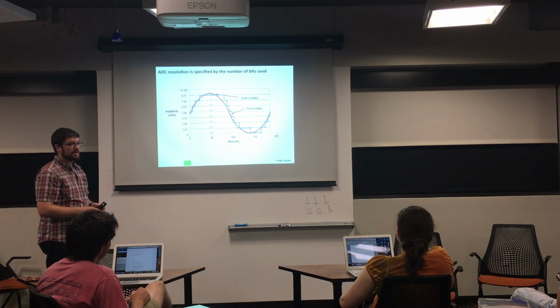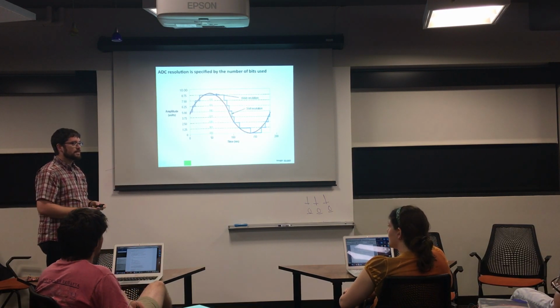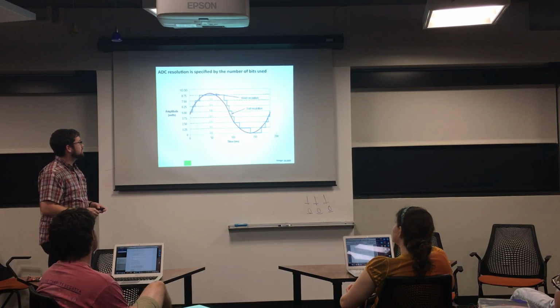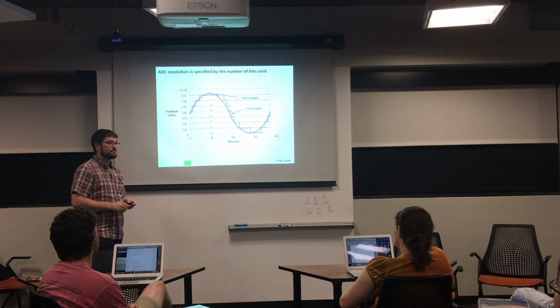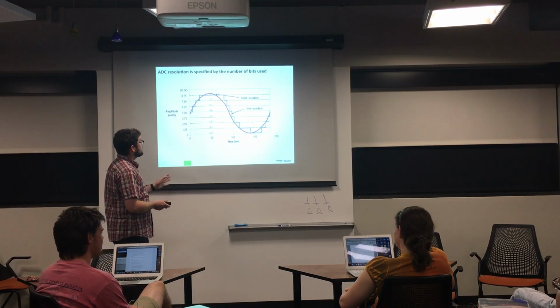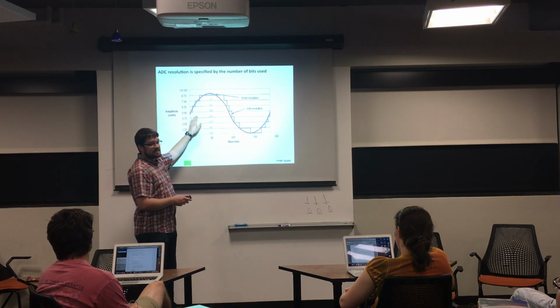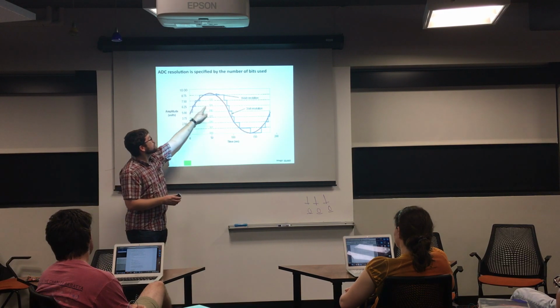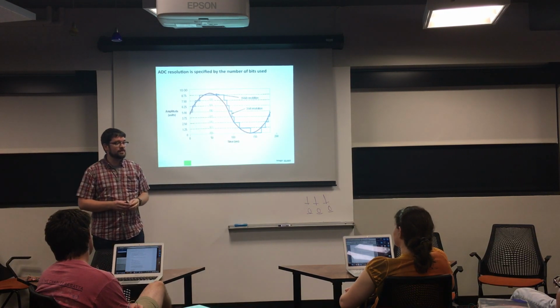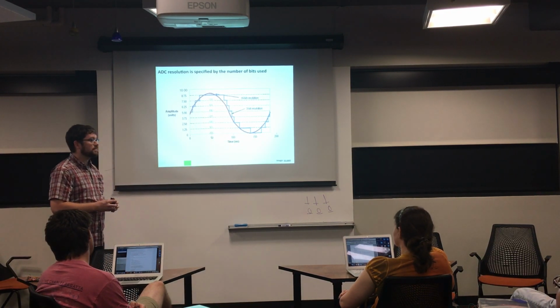I mean, if you're thinking about, I'm going to load some sample to 10 megapascals normal stress, is it good enough that each step on your analog to digital converter is over a megapascal? Probably not. But if you go to something that has 16 bits of resolution, then it actually looks almost exactly like the original sine wave because we've got so many more bits.